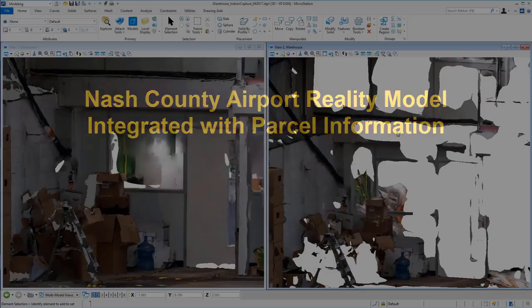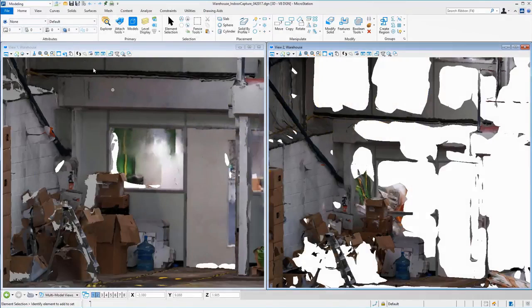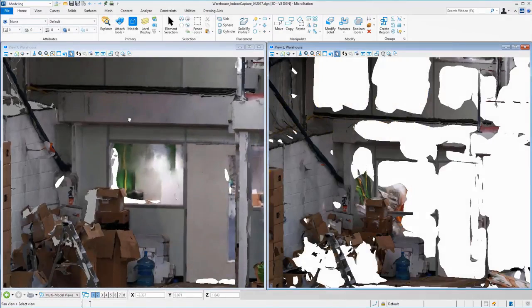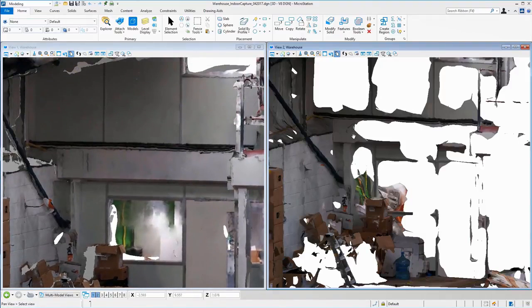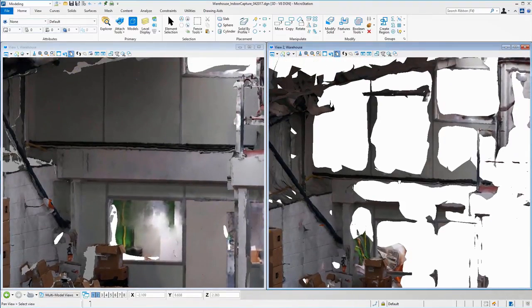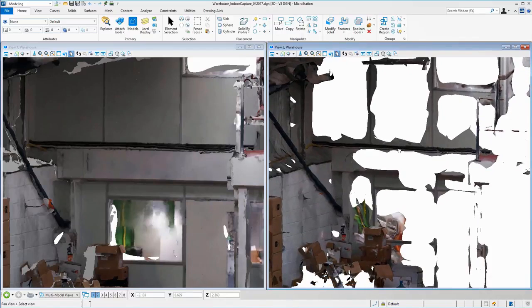I would like to show you one more sample here. On the left, we see what was done with photogrammetry and with LiDAR. On the right, you're seeing just what was done with photogrammetry. So as I mentioned, areas that have no change in color, very flat, just no deviation and no texture, don't come out very well in photogrammetry. So you'll see on the right, those flat panels kind of just came up as voids, where those are a great case where you could just use LiDAR on that part of the wall to fill that part in for you.